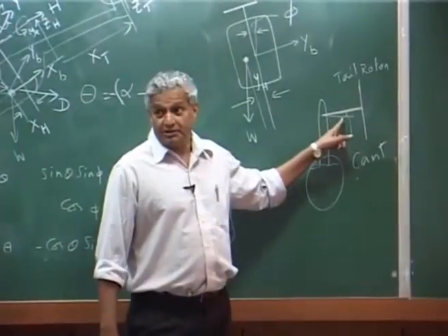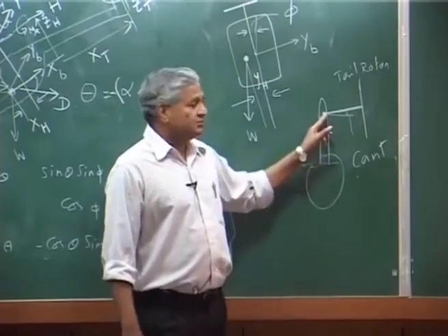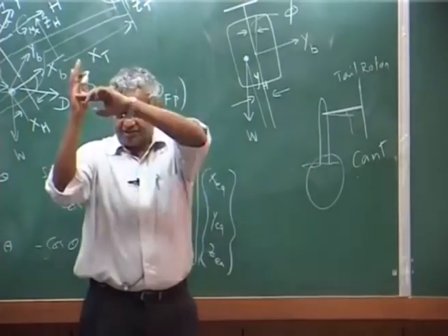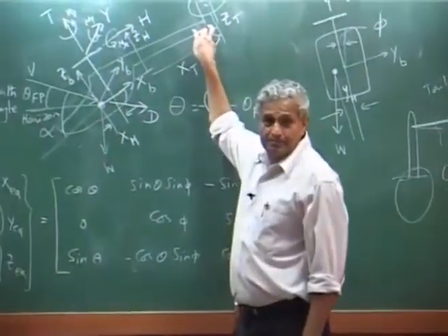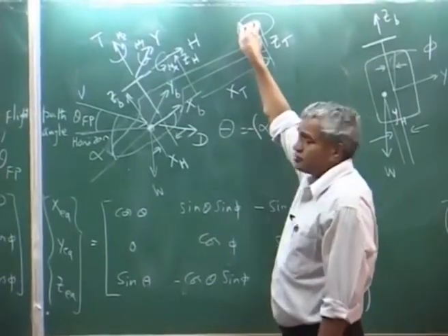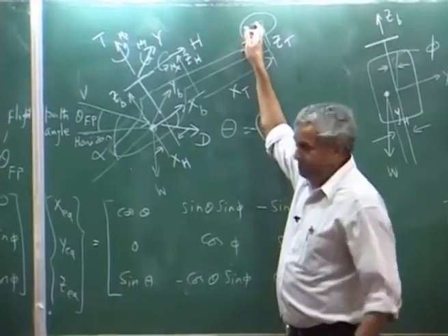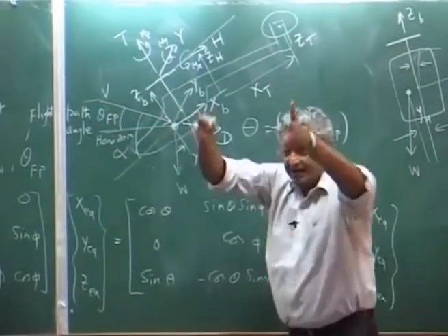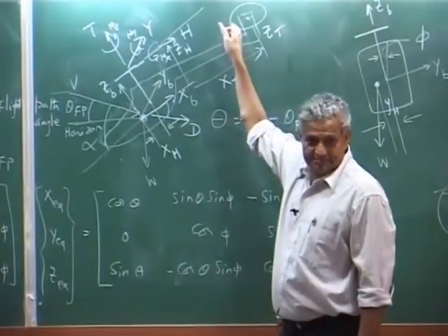And the distance, these are all important. You need the vertical fin because you want to mount the tail rotor at a slightly higher position from the boom. You may ask why shift it up; that is a configuration choice, because the wake from the main rotor, you do not want it to hit the tail rotor.